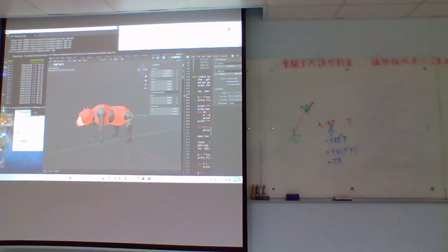So Z is always the most likely axis of rotation during the motion. This is Y, this is X, so here I aligned it. But my hinge joints, my 1 degree of freedom, my actual revolute joints, I always set them up so that the Z-axis is the axis of rotation, and the home position is always 90 degrees, and they're all like that.